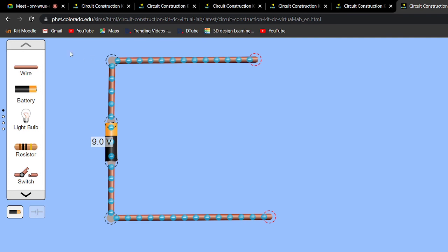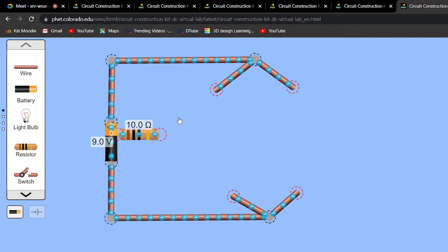And this is the first circuit, with all the elements. And this is to find the VThevenin, where I removed the 40 ohm resistor and found the VThevenin across it. This is the Thevenin's resistance circuit. I put a voltage source and an ammeter, and divided using Ohm's law and determined the equivalent resistance in the circuit, which is the R Thevenin.